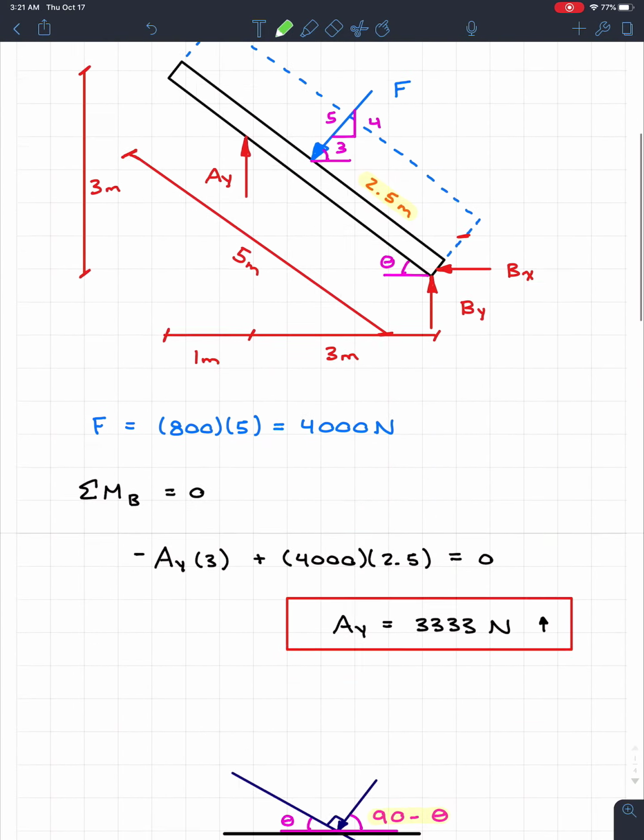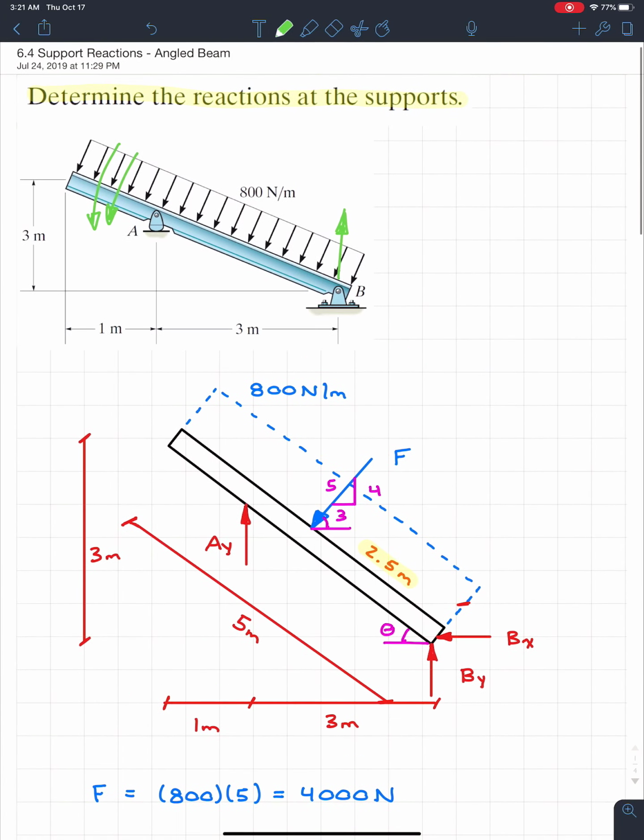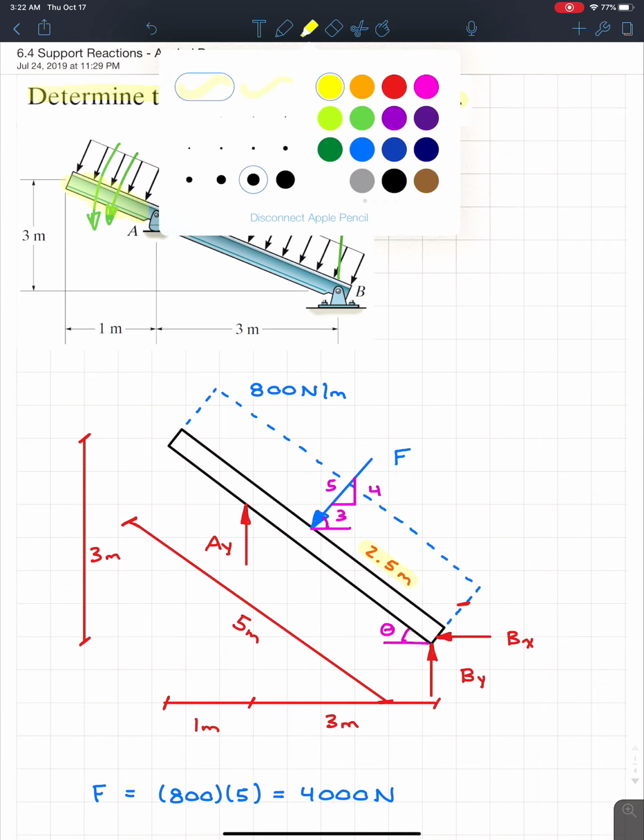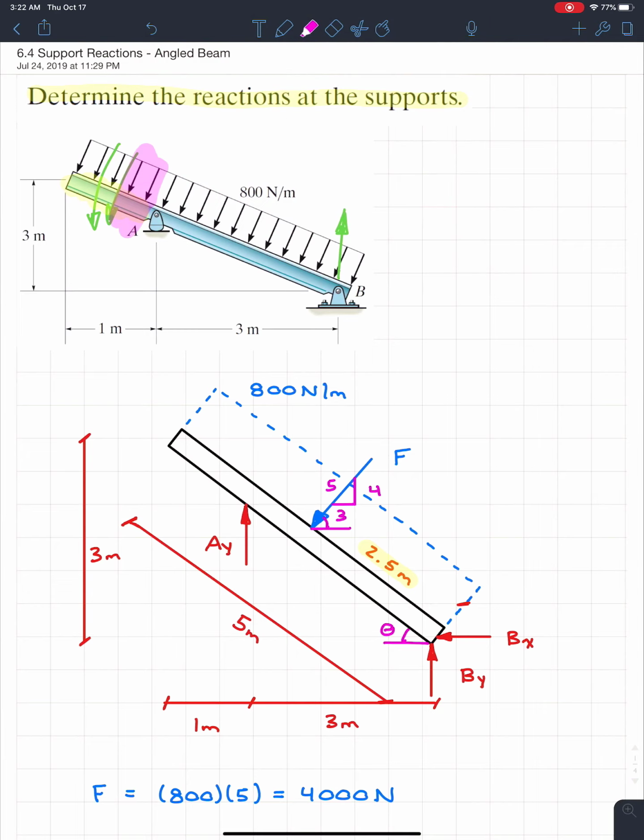And we see that it's very low because the cantilever side, this cantilever, it's not huge. If that went way over, let's say a couple more meters, the reaction force, of course, would increase a lot. And if there wasn't any cantilever there, so if I were to remove everything in pink on this side, then the reaction at B would start going in the actual upwards direction, which is what most of you guys expect.